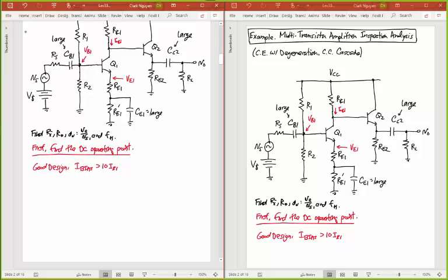So this is the base current going into Q1. And this current right here is that I bias current, the current flowing through those resistors. This is basically saying that the current for the stage before the stage that's being biased up should be a much larger current than the base current going into the next stage. Okay? And so that's just a design point. If you want a good design, this is what you want to do. And hopefully you're doing this for your current lab. You're going to need to do this for lab 6 too, which is going to be a multi-transistor type lab.